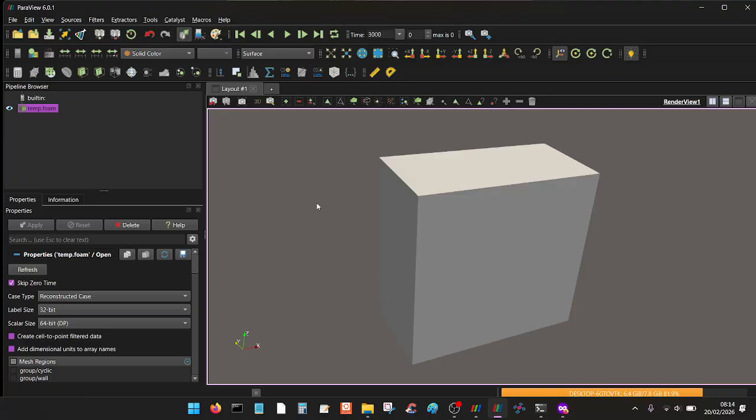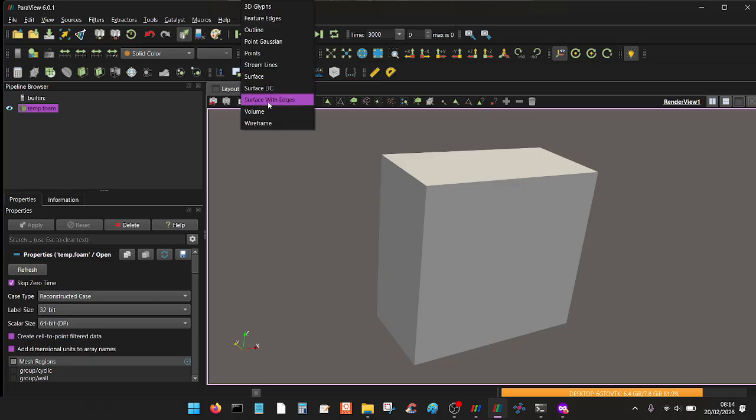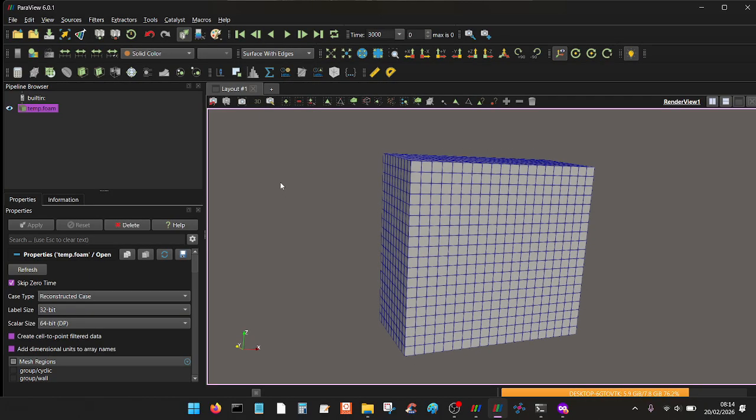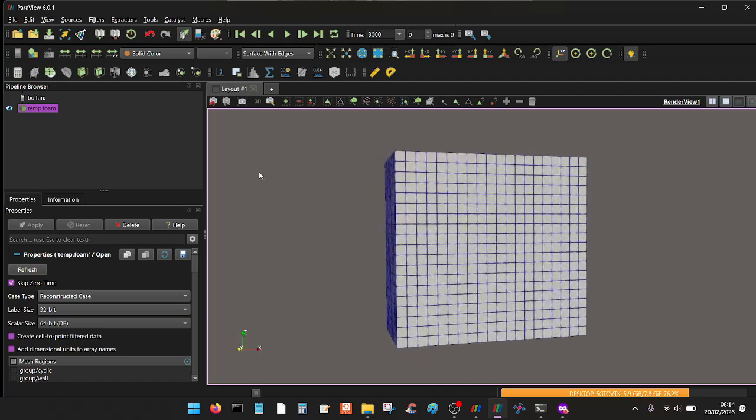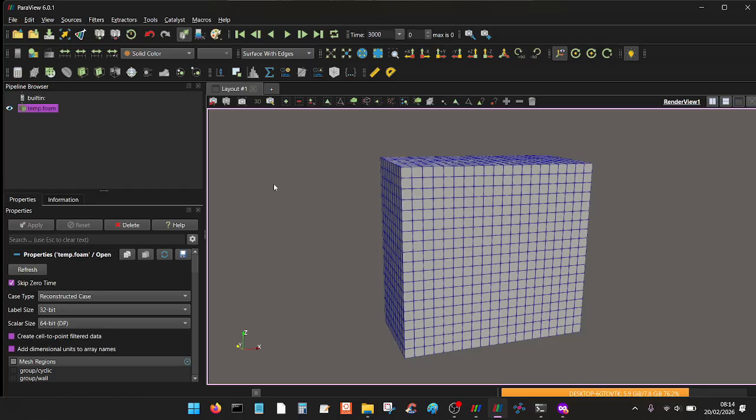So when I load the flow solution into ParaView, skip 0 time. What it actually does is load up the block mesh that's in your constant polyMesh directory. So that's the block mesh. Because I meshed it quite large, I then scaled it down by a factor of 10.